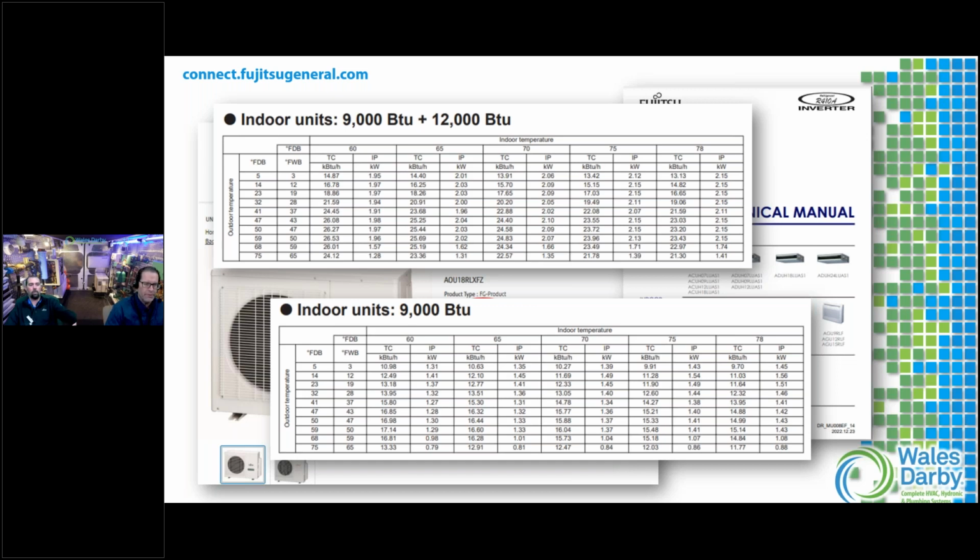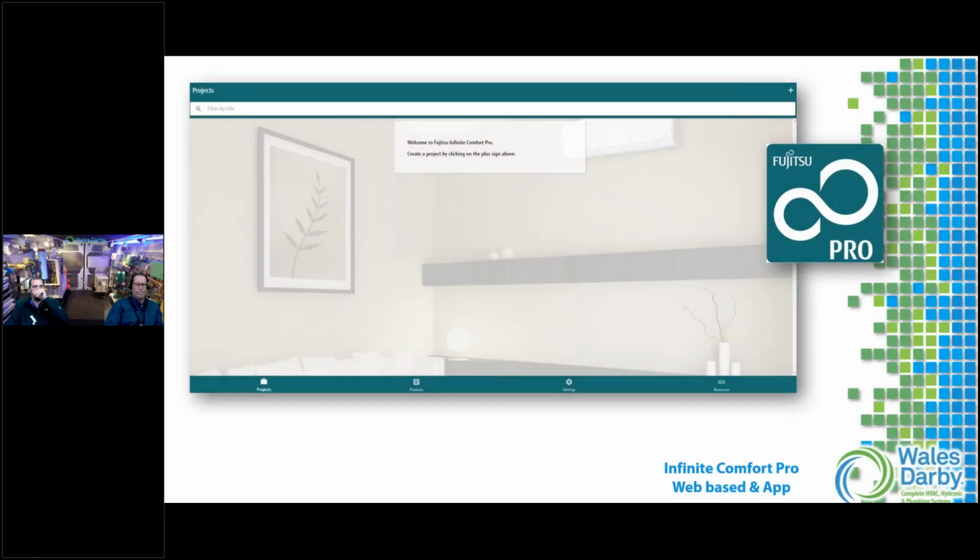He certainly gives what his needs are off indoor temperature. Exactly, indoor and outdoor, and set point. So there are a lot of variables playing a part, and this is why we see some of the efficiencies that we're talking about when we get into COPs and all that. So after we figure out the load, we know what we need for the space, and we've picked some units, maybe a 9 and a 12, we'll use that same example to keep moving.